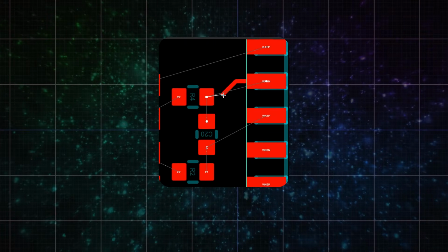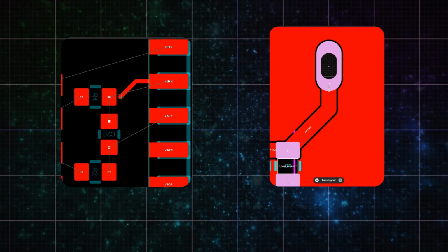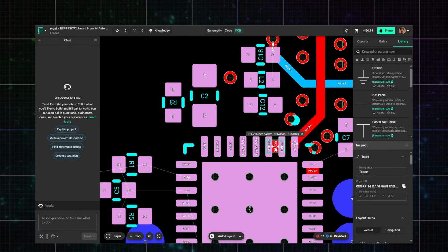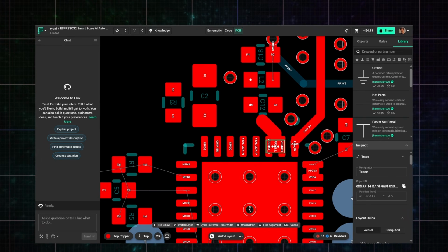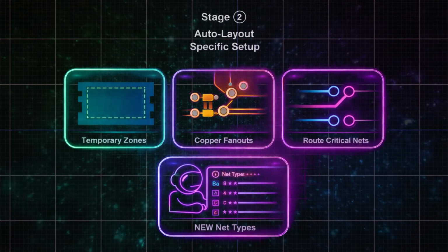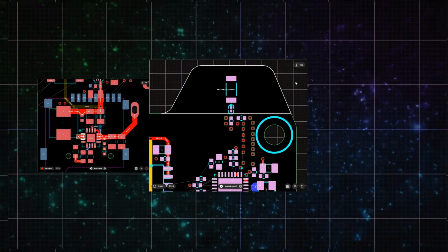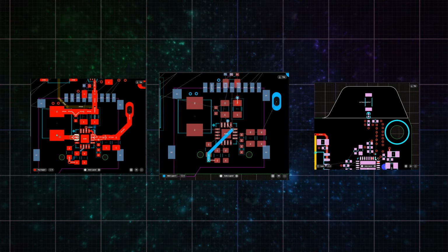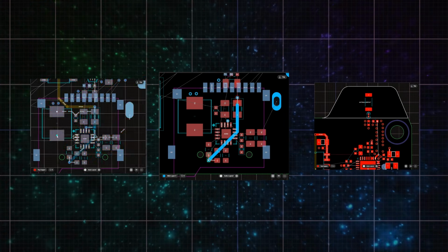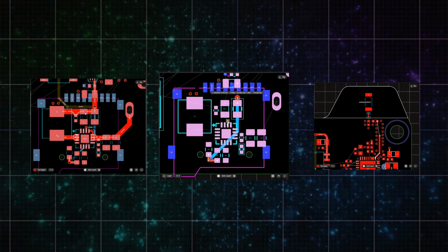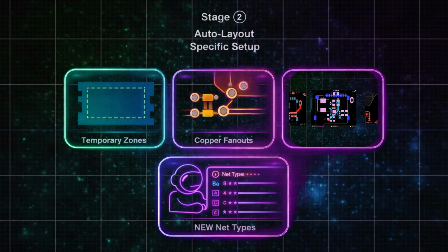This model is not currently capable of resizing trace widths for nets. It also cannot alter the keepouts on net copper. This means that you need to intervene before you run the job or after the job completes to add neck downs or fanouts when large trace widths like power need to connect to small pads. Similar to our previous model, the focus of this agent has been on reliably routing the most common signals which our users face on their projects. We recommend routing high-speed, sensitive analog, as well as sensitive or high-power copper manually before the job begins.